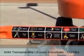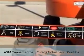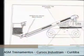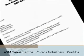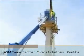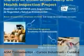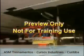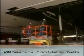Most lifts are equipped with various safety features. Never remove, bypass, or use these safety features for any reason other than specified by the manufacturer. Never modify a lift without written permission from the manufacturer or other qualified entity. If modified, the lift must be at least as safe as before modification. Employers should also be aware of local and state regulations and ensure compliance with those laws. Only authorized and trained persons should operate an aerial lift.